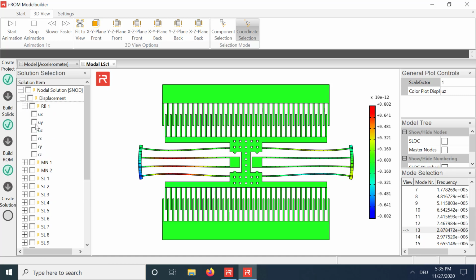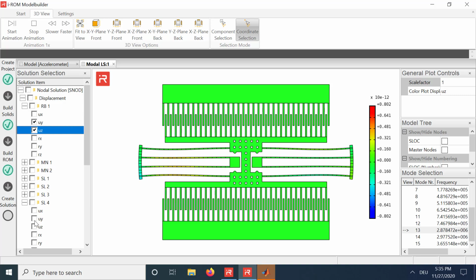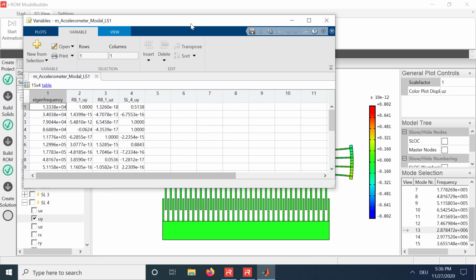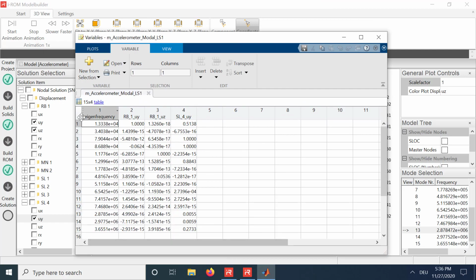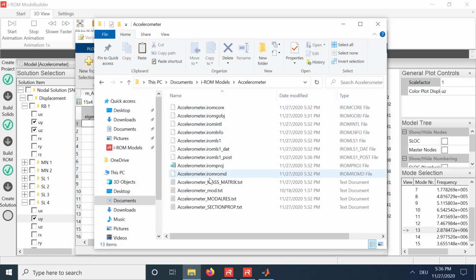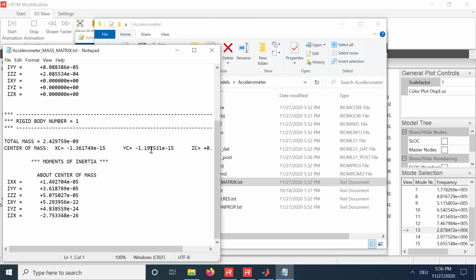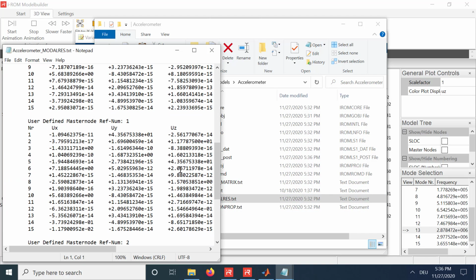Eigenvectors at the mass body center points, at master nodes, or at spring location points can be listed in our graphical user interface. The numbers indicate modal amplitudes in operating and cross-axis directions, and help you to optimize your design. Cross-sectional data of beam elements, the inertial properties of mass bodies, and modal analysis results are likewise written to result files in the working directory.